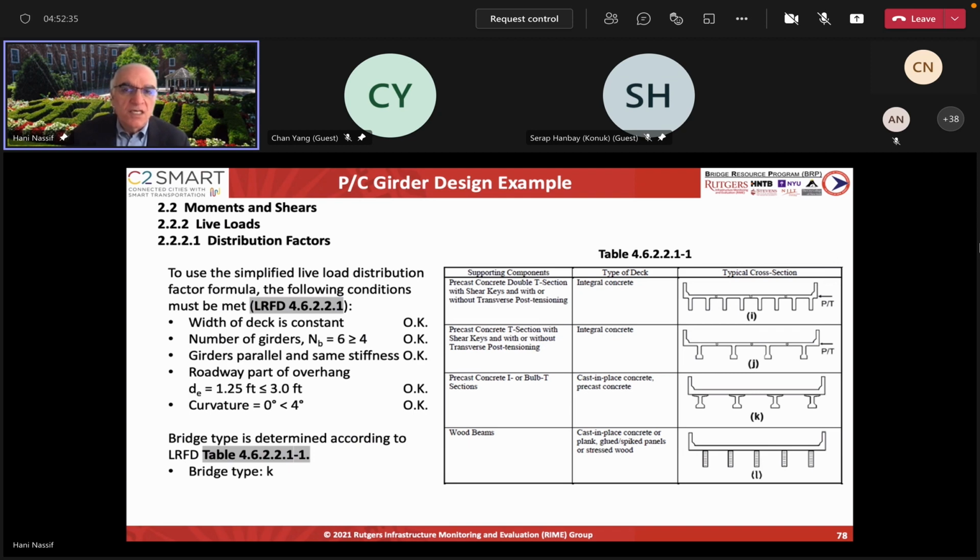That's why the new LRFD differs from what was done before: it is about how many wheel loads will be distributed to each girder. There's a difference in the distribution, but the total moment per girder should be comparable between LRFD and LFD. However, the way distribution factors are interpreted, they're not the same. So here we take one lane moment and distribute it to the girders, or we take two lane moments, put two trucks side by side, find the total moment, and then distribute that moment into each girder, the interior girder and the exterior girder.